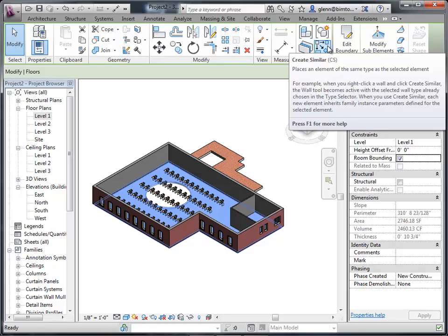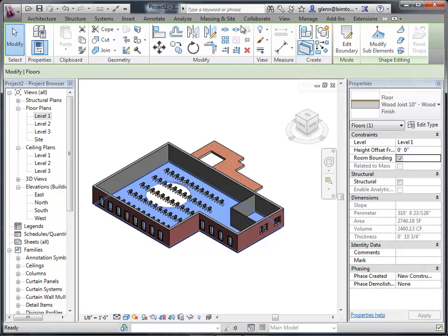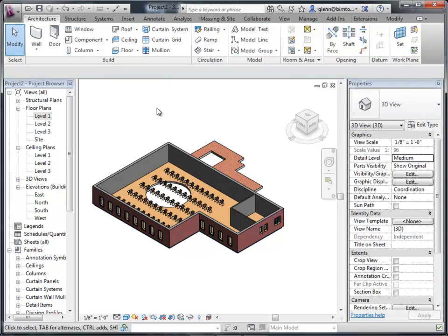So you get to specify how far that overhang should be. The other issue you have to worry about is whether this roof is going to be sloping. So relative to this wall, is it going to be sloping up, or is it going to be flat? And that's where all the beauty and the pain in roofs comes, in those two different decisions. Because you can almost always get the walls. It's really about getting what you want by understanding how the sloping works. So let's show you how that works.